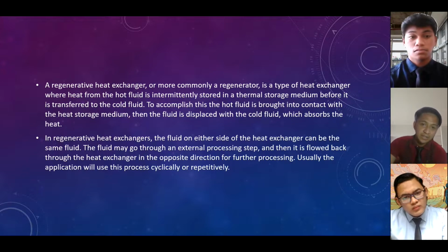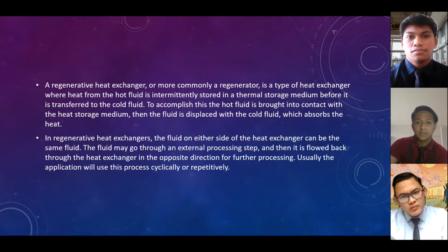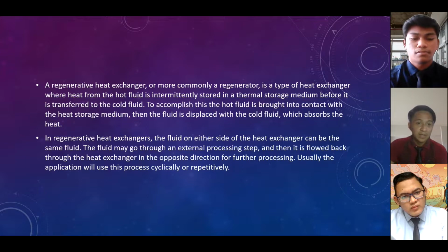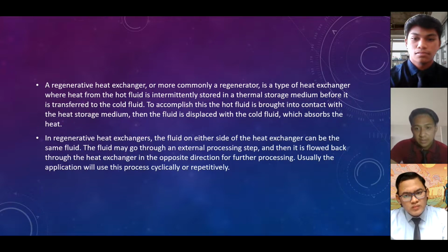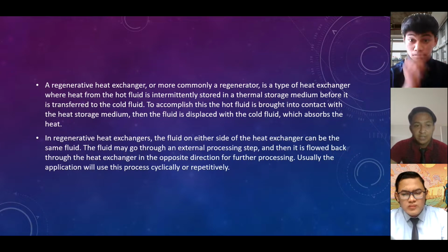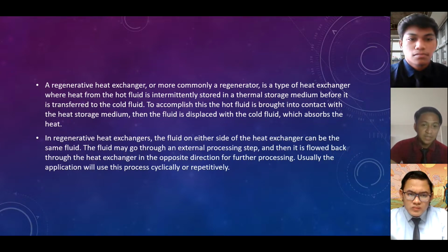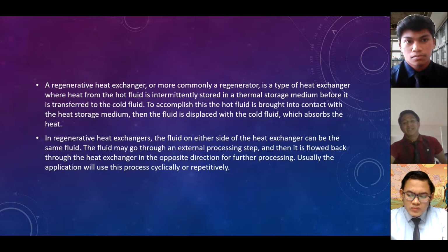Then the hot fluid is displaced with the cold fluid, which absorbs the heat. In regenerative heat exchangers, the fluid on either side of the heat exchanger can be the same fluid. The fluid may go through an internal processing step and then flow back through the heat exchanger in the opposite direction for further processing. Usually, applications will use the process cyclically or repeatedly.